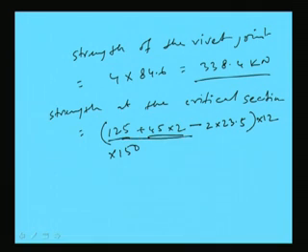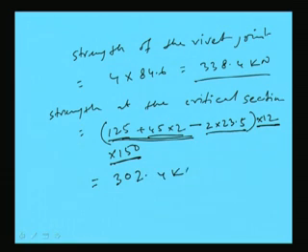So, total width will be this minus reduction due to hole into plate thickness into allowable stress will become the strength, which is becoming 302.4 kilonewton.